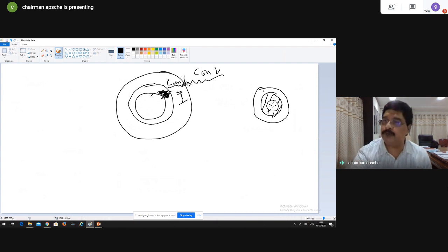Now heat transfer should happen this way, radially inward. And now insulation is the first layer, metal is the second layer. Now because of the thickness of insulation, conduction resistance increases. Now there are two resistances.